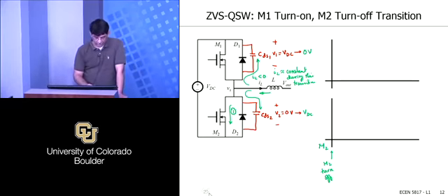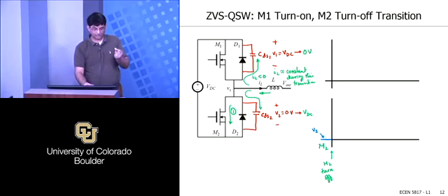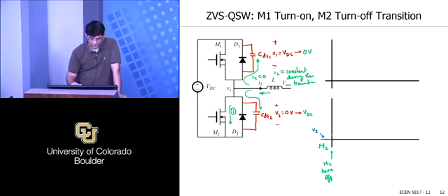So if we looked at voltages, let's look at voltage across M2, V2. Initially, it's going to charge up capacitor 1, and I'm also going to ignore that slight period, the amount of time it takes for the channel current to go to 0. That's a pretty short time. So the current just splits, starts charging these up, so that this voltage will rise.